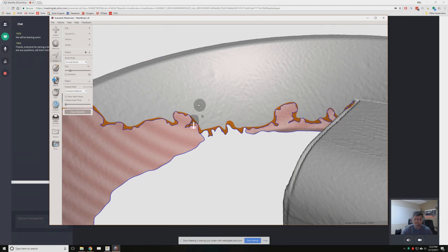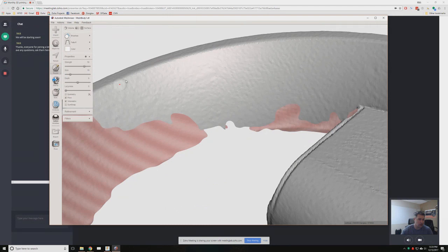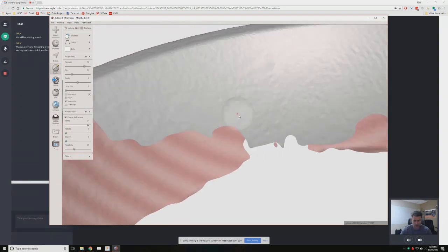If you go into Sculpt, you can use really any of these brushes, but smoothing, robust smooth, is probably a good one. Go down here to refinement and make sure refinement is turned on. You can turn smooth down, you can turn reduce down if you want, as long as refine is turned up. So what you see as I click on this, let me zoom in a little bit here, is that it's actually based on the size of the brush, smoothing out those areas and kind of normalizing them. If my brush is bigger, then it will work over a bigger area.